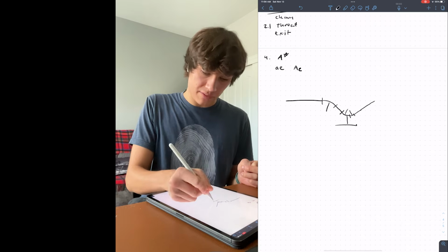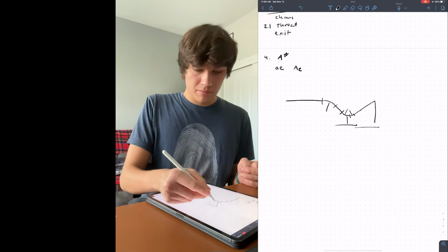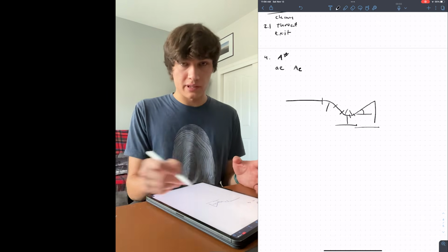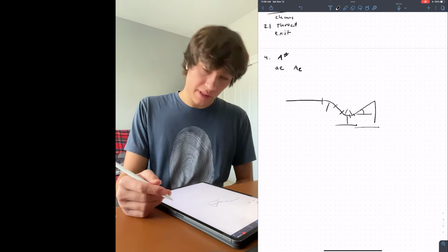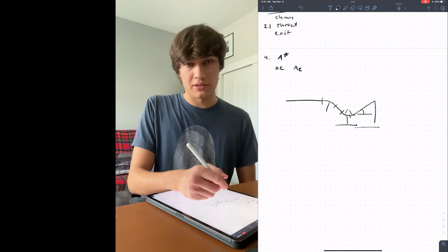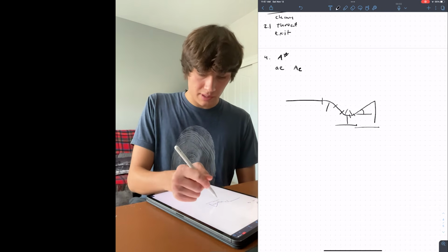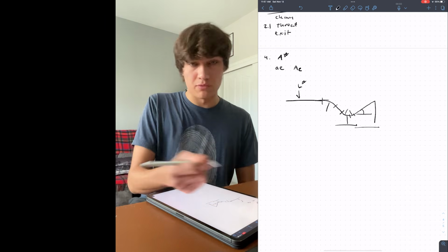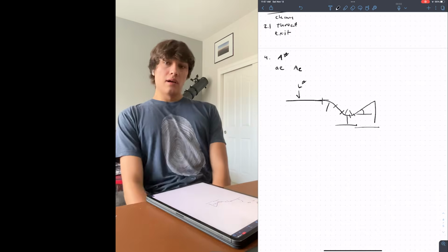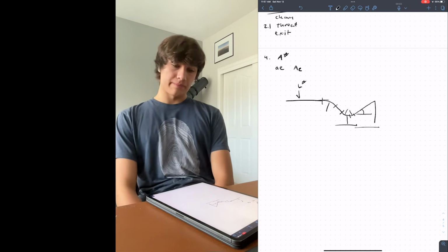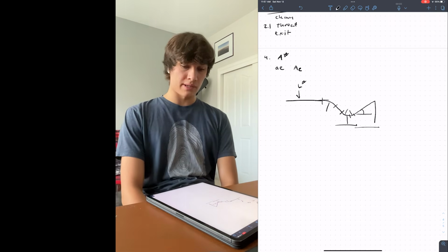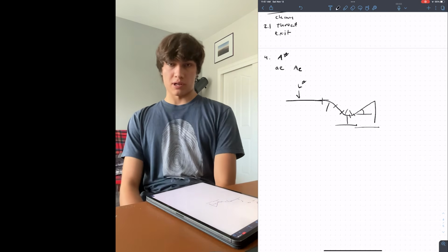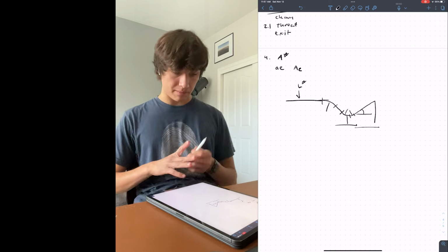At this point, you should already have the area here and the area here. You'll find what this angle is as well, and you'll be able to find the length if you want. And then you can choose some contraction ratio, usually like 3 is pretty good, between A star and this, and then the length will be governed by L star through the volume relation that I showed you above. And that is basically your rocket engine. That's what goes into sizing the rocket engine. This represents the idealized shape and the idealized chemical process that makes your rocket engine work.